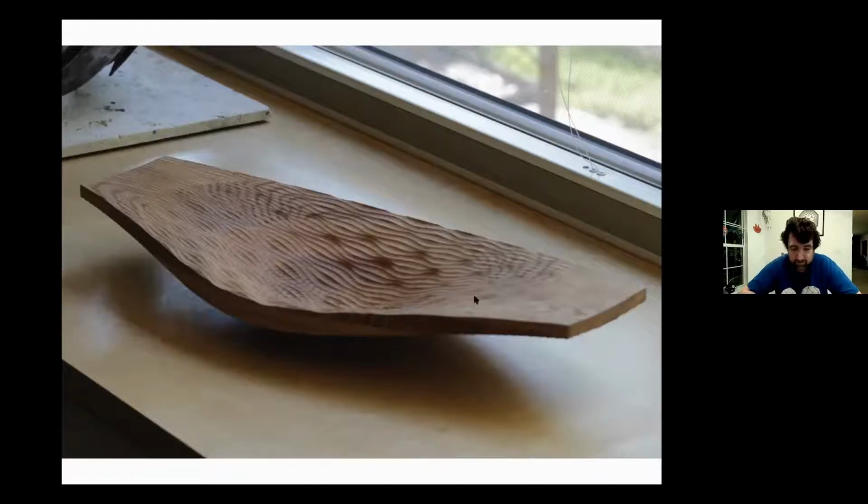This is made with a 5/8 of an inch ball end mill. So you're moving a hemisphere with a 5/8 inch diameter through the wood. And as the central bottom of that sphere moves under the path that we describe, the wood that's removed varies depending on how the different levels of cutting relate to each other.